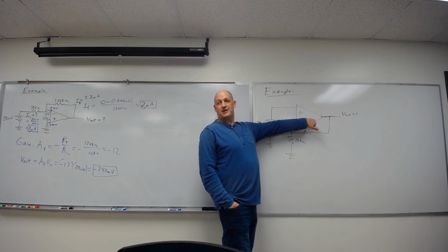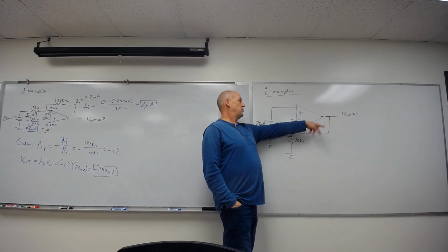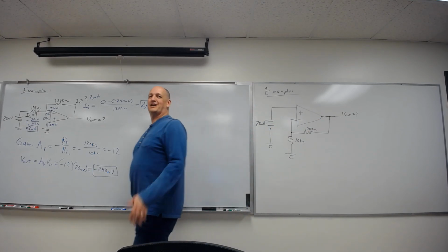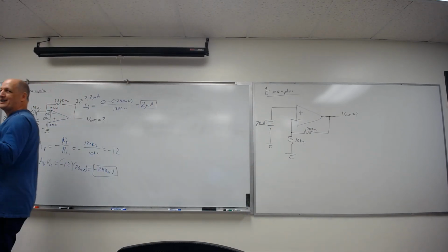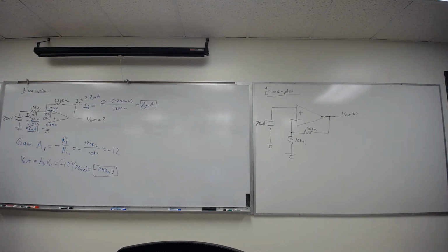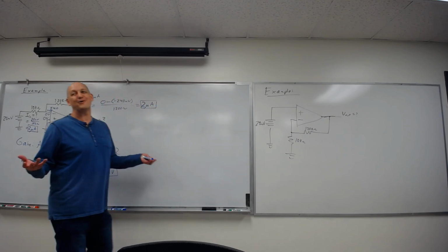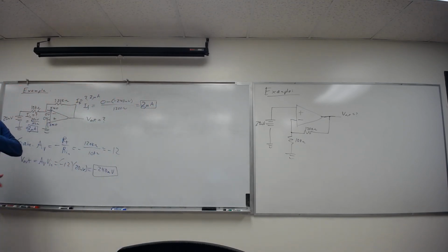I can just plug one in, it's going to work, because if it has a little more gain, then I'll end up with more coming back through my feedback resistor, reducing the gain. If it has a little less, I'll have less coming back, letting the gain be bigger, and it'll work out to be close to the same. Obviously there are actual differences, but close enough. You would think electronics is all super precision, but we use 10 and 5% parts everywhere.